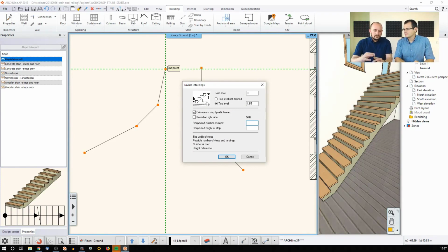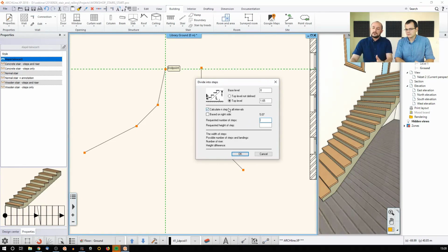Yeah. You can, again, use values. You can mark those spots with tiny dots or something like that. This could be anything. The idea behind this is that then you can set up where you would like to find yourself when you finish this staircase. So you can change this value. Let's just go with 2.5, for example. And then you need to decide how many steps you would like to see along this staircase. Let's just go with 12 first. And the software calculates everything.